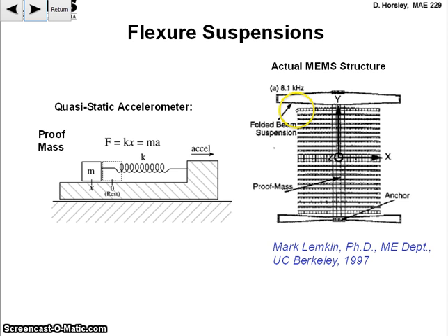Anyway, this is a proof mass here, right? This is the thing that is M over on this cartoon, and then the springs are these two springs at the top and the bottom. And you can see in these regions, this is the anchored part, this is the anchored part. So this whole thing is allowed to move. And what's happened in this thing, the proof mass has moved in the minus y direction, right? So there's an anchor here that's fixed in place and another anchor here that's fixed in place. And so you see that one spring is becoming extended in the negative y direction and the other one's becoming compressed. So this is a typical way that you would see a MEMS suspension moving.